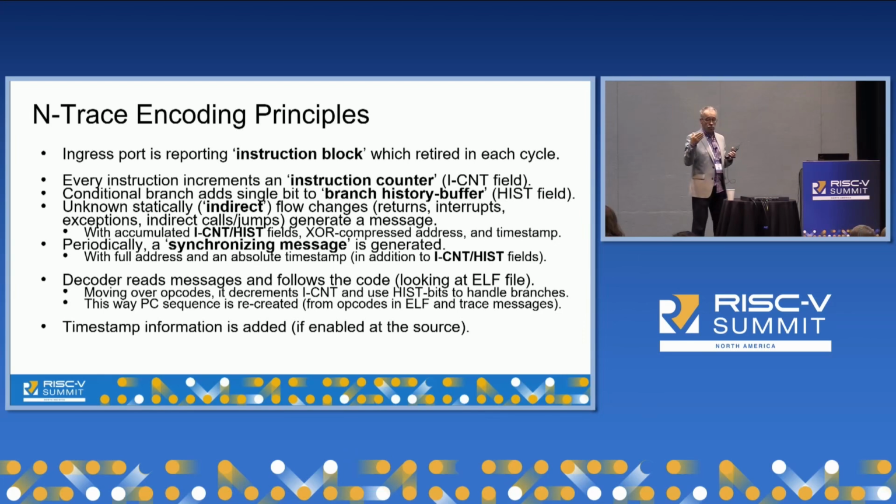And also, just to make sure the decoder can act from the middle of the trace, because sometimes you have 1 gigabyte of trace, you just can't afford decoding from the very beginning to the end. So periodically there's a full drop of everything. So you drop an address, and you start decoding from there. So the decoder can take any piece of trace in the middle, and then it can synchronize. So that's it. And the decoder does it the other way. It just follows the code.